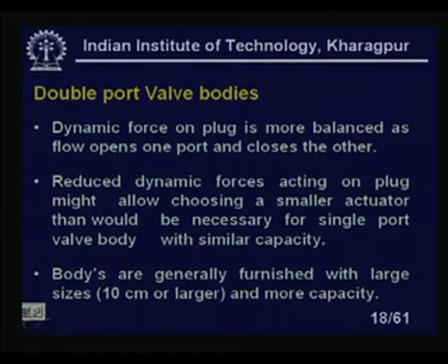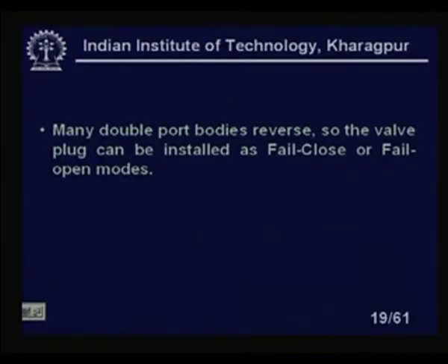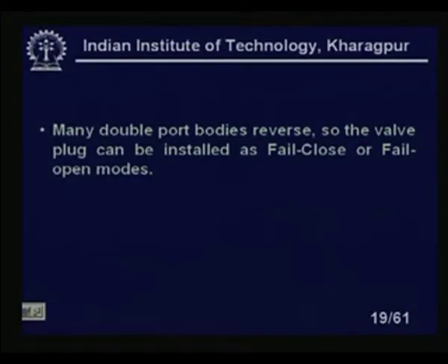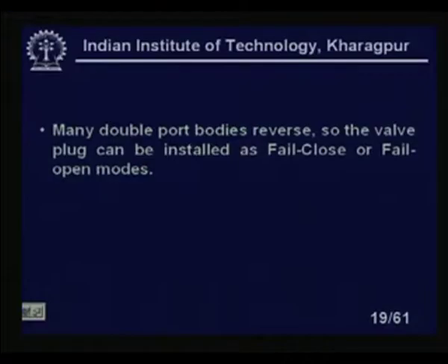Bodies are generally furnished in large sizes, 10 centimeters or larger, and the capacity is also more for this type of valve. Many double port bodies are reversible, so the valve plug can be installed for fail close or fail open modes. We have seen that the valve can be used as fail open, push to open or push to close.